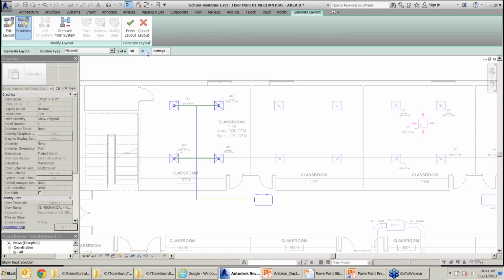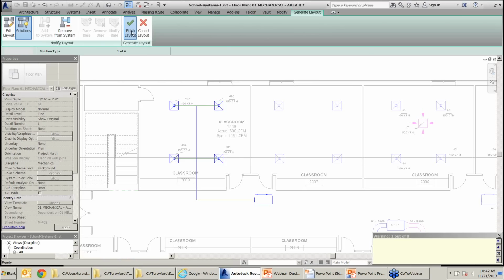Now, I know ahead of time, I can see some lines are green. That's my branches. Some are blue. That's my mains. And there's a yellow, orange, gold one. I'm going to call it yellow. That, unfortunately, tells me that Revit knows already there's going to be some error with that one. So something's not going to connect right.